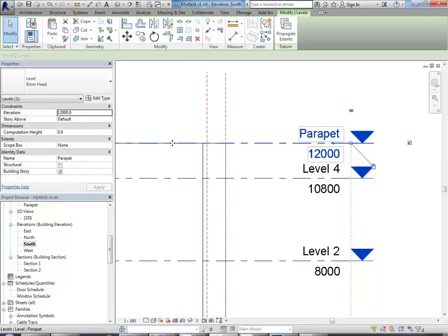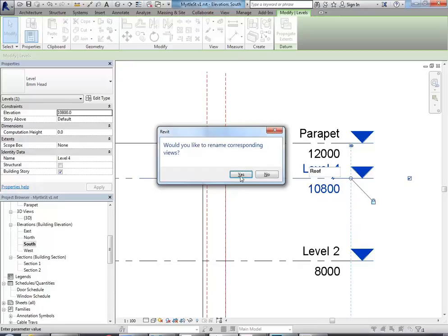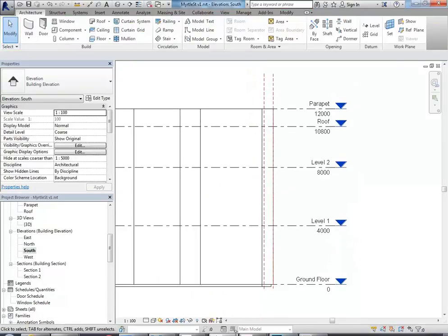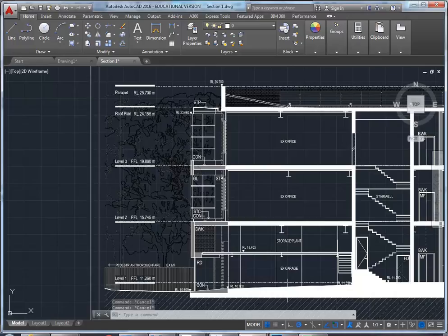Right, because I've set the top of my wall to that level. I don't want to go and change all of that. And then I can call this one now roof. Notice I'm not worrying too much about those heights. It's easy to change those afterwards. And that's the beauty of Revit. You can just set up the levels that you need, the number of levels, and just worry about those actual height values when you have time. Doesn't really matter.